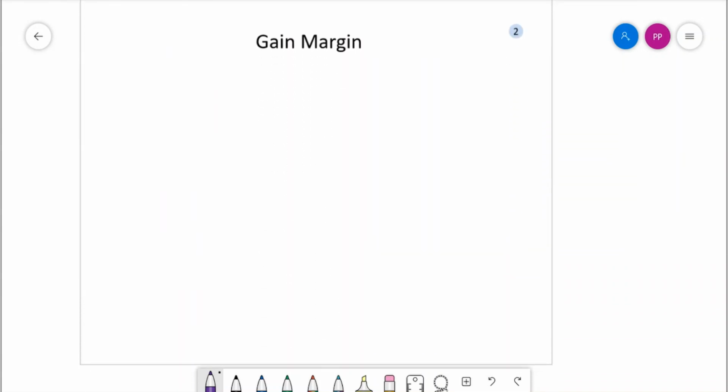So we start with gain margin. As we have seen that on the polar plot we have a crossing like this, and this magnitude is A. So here we can say that the gain margin of a stable system can be defined as the factor at the phase crossover frequency by which the magnitude, which is less than 1 for a polar plot for a stable plant, of the stable loop transfer function can be raised to drive it to the verge of sustained oscillation or instability.